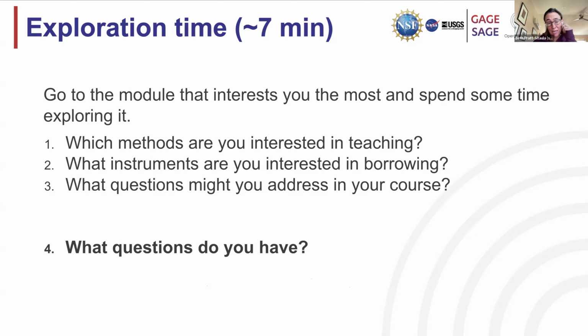And maybe I'll just, because I love GPS, mention that there's a GPS unit on your GPR. So once they get the acronym straight, you can at least give them an introduction to the GPS, even if you don't decide to also get a base station. If you're just running your little GPR cart around with the rover on top of it, it'll have a couple meter accuracy, which is generally enough in most cases. But if you wanted to additionally bring in the GPS, you could order a base station and have them learn about the base station rover combo. And then you would really for sure know where your GPR is at all times.